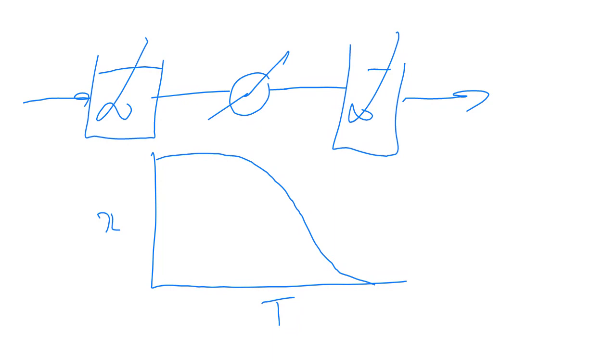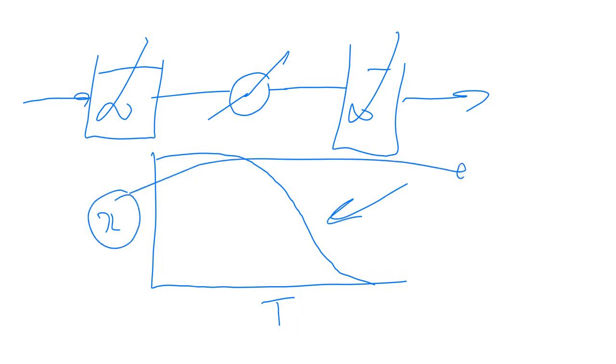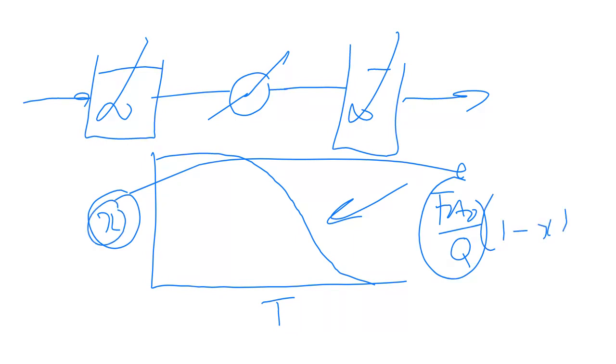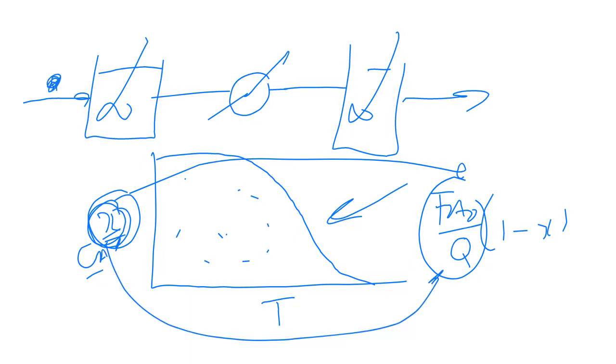Remember, this whole figure, X, relates to a specific inlet molar flow rate state divided by Q. And then you multiply this by 1 minus X to get a concentration. So this is actually a concentration versus temperature figure. X is just another way of representing a change in concentration. And if I now want to calculate something on this diagram and relate it to an X value, this must be related to this inlet molar flow rate, okay?